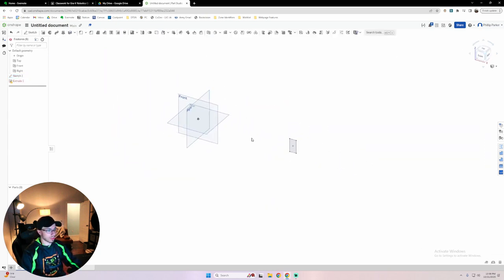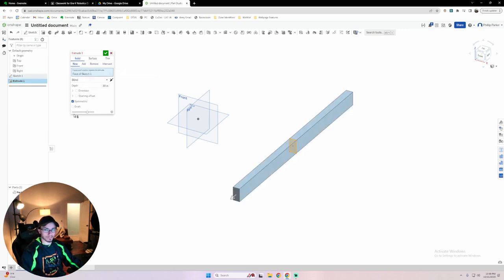Okay, so now it's away from the origin. This is good. Okay? We're going to fix this sketch. It highlighted itself red because it broke the sketch, right? And it gave me a little warning. It says extrusion could not generate properly, missing one of the selections. I double click it. It's missing the sketch from face 1. Okay, I just delete. I reselect it. Boom. Now we're good. So, why might this be useful? Well, now we've created this off and free space, which is good. Okay, we're going to click done.